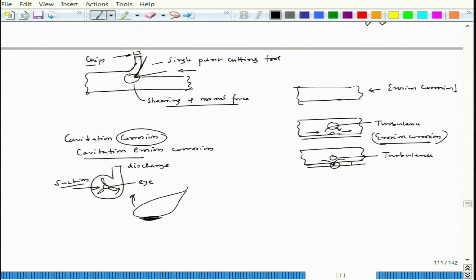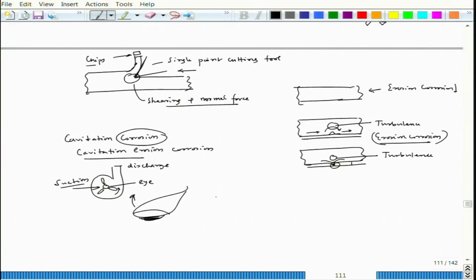spots of defects. In fact, at times this back portion could develop so much defect, a kind of dent or pit, that it might get fractured, because it gets weakened and weakened as it is also moving. There is a stress effect, and at the same time those small pits are forming. So, this happens due to bubble formation and its bursting process.